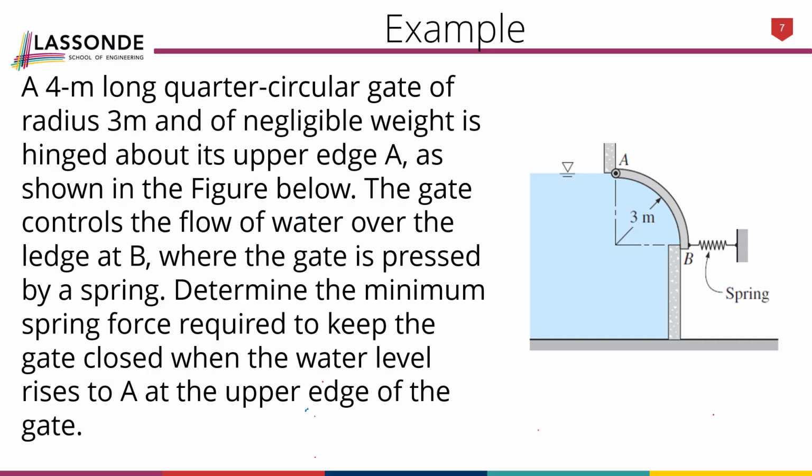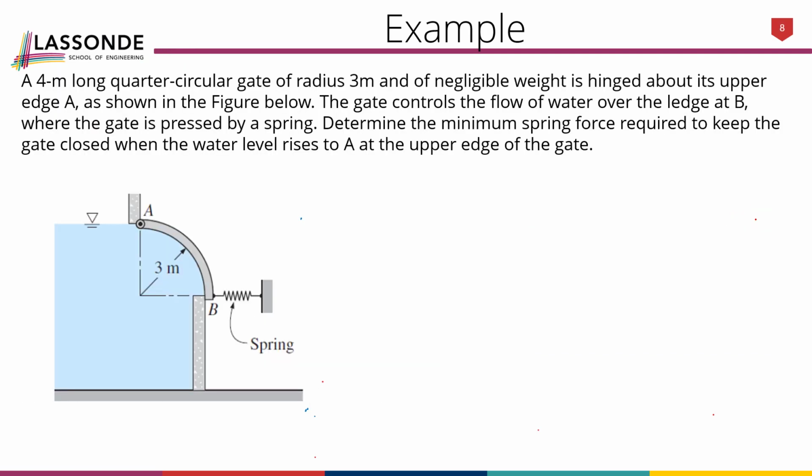Okay, let's solve an example problem of hydrostatic forces on a curved surface. Here we have this 4-meter width quarter circular gate. Its radius is 3 meters. It has a negligible weight. It's hinged at A, and there's this spring here where we want to find the spring force that holds that